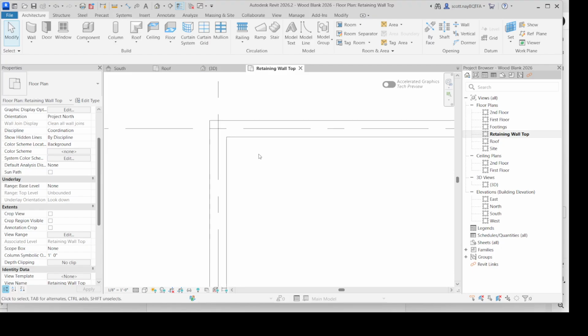If you really want to, you can create something that's made out of butyl or some other soft, malleable thing. So the purpose is, one, to keep the wood from connection with concrete, which will destroy your wood over time, but also any of the tiny gaps that would let air flow through, it seals that up.